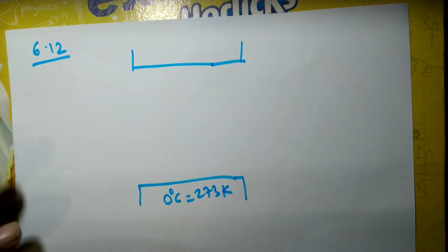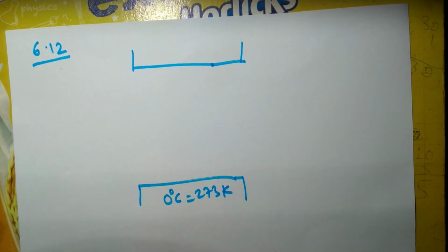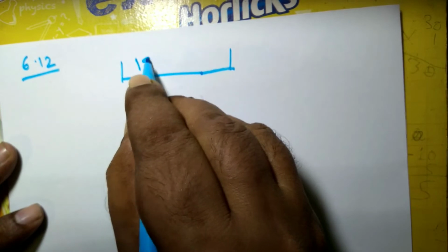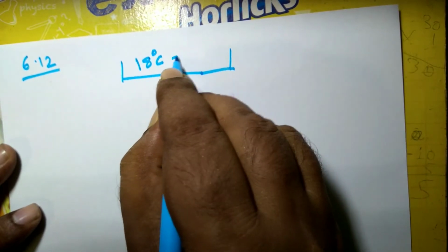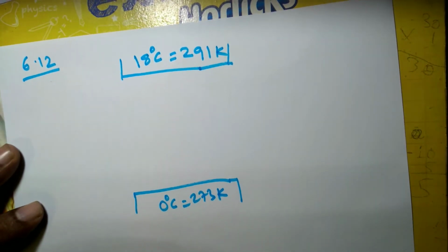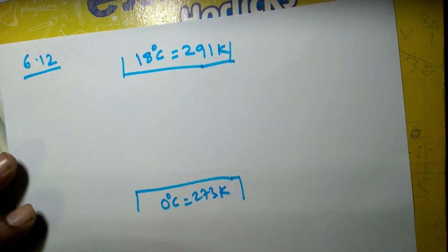So in this case, the high temperature is the mean temperature of the cooling water circulating through the condenser, 18 degrees Celsius. So this is the high temperature, and 18 degrees Celsius in terms of Kelvin is 291 Kelvin. So the minimum electrical work is to be found out.